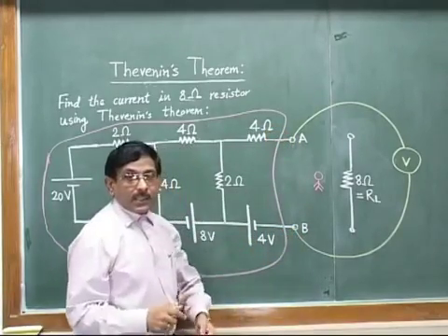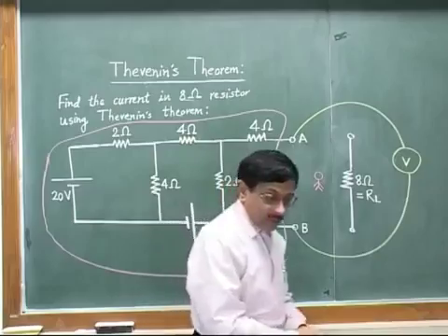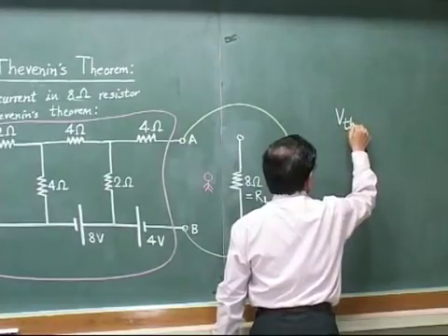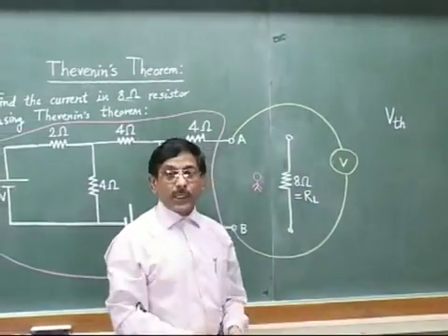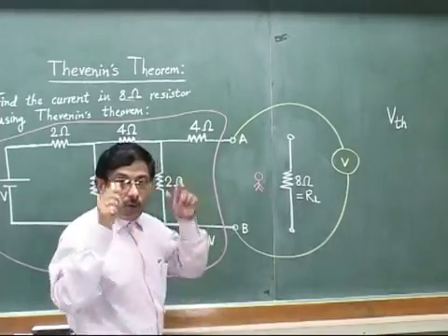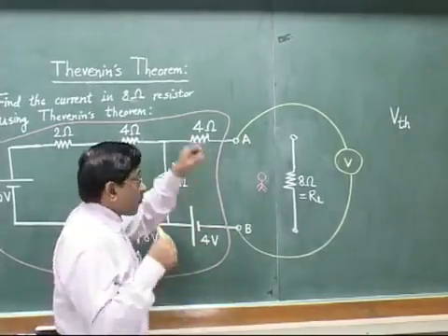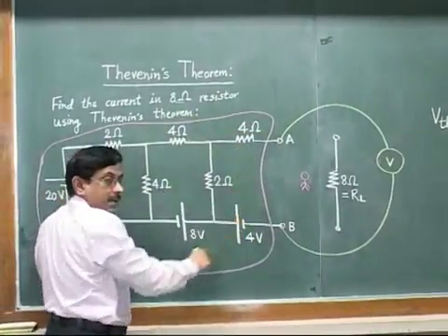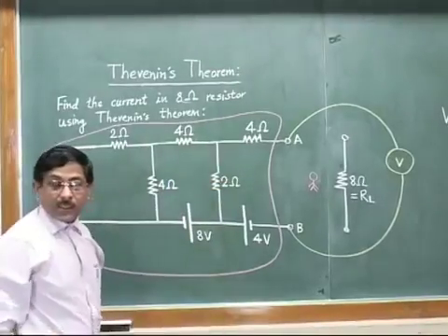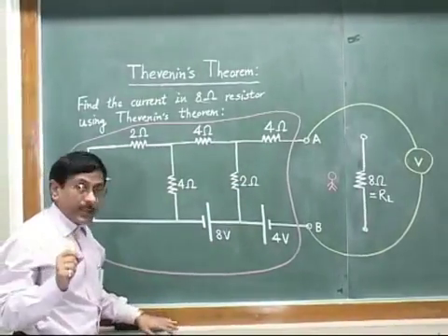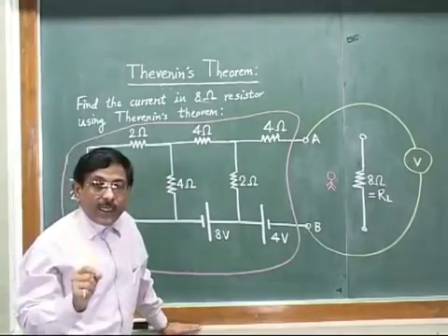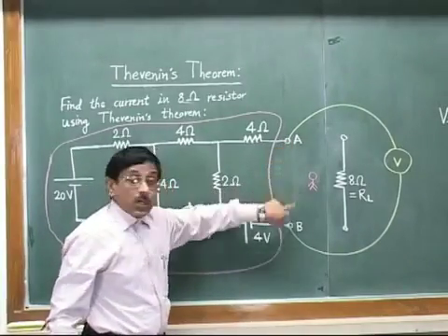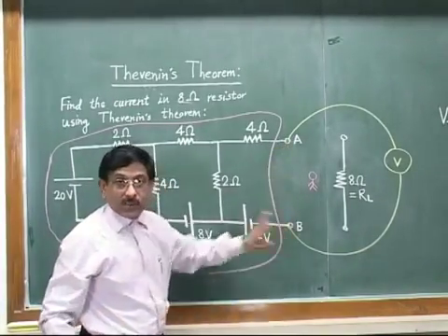Thevenin said that this is the open circuit voltage, and normally it is denoted by VTH. So VTH is nothing but Thevenin's voltage, but its meaning is that it is the voltage or potential difference which exists between points A and B due to the action of this entire circuit. So that we now call Thevenin's voltage. So again I repeat, the meaning is that Thevenin's voltage VTH is nothing but some potential difference or voltage which appears across the open points A and B, or these two ports.